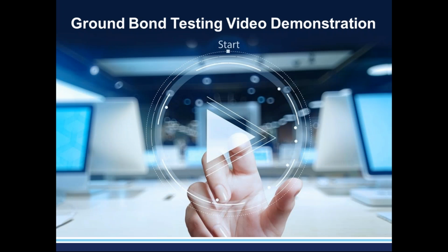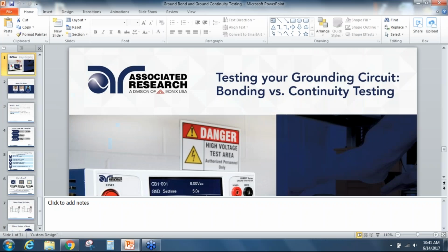This brings us to our video demo section. I would like to demonstrate what I mean by ground continuity and ground bond circuit. First I'm going to show you a ground continuity test being performed on a soldering iron. So let's take a look at that really quick.